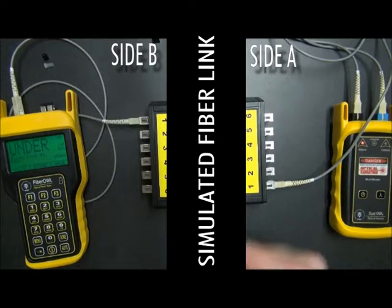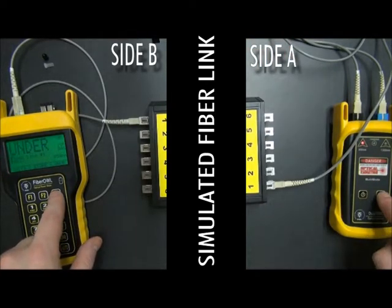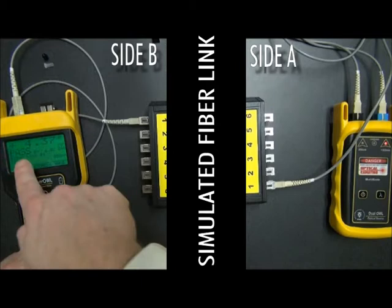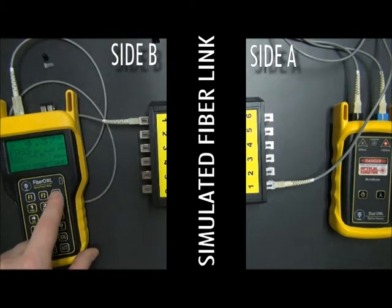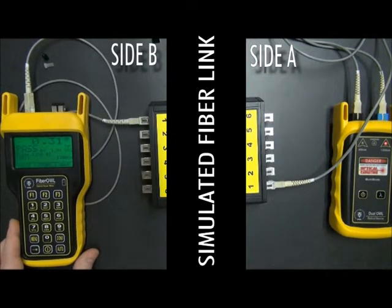So what we need to do is change to 1300 on both sides. On the light source, make sure it's not blinking anymore. And then you can see there's a reading here. Of course, we're still set at 850, so we need to press F3 to switch to 1300. You can see now we have another pass reading.